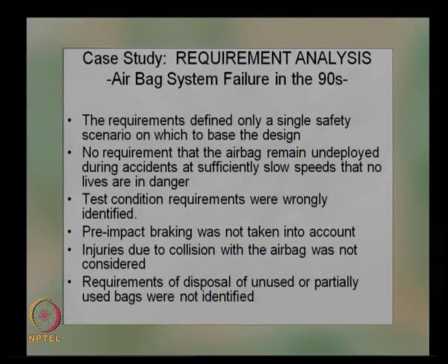Then again, pre-impact braking was not taken into account. Normally before the accident, brakes will always be applied by the driver, and that actually reduces the speed of the vehicle. Because of this speed reduction, the driver will be moving forward and hitting the steering assembly, and that was not actually envisaged in the test condition. It was always assumed that the airbag should deploy only after there is a collision.